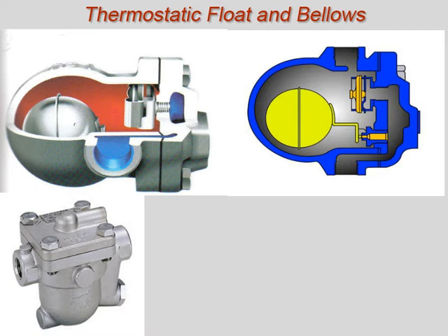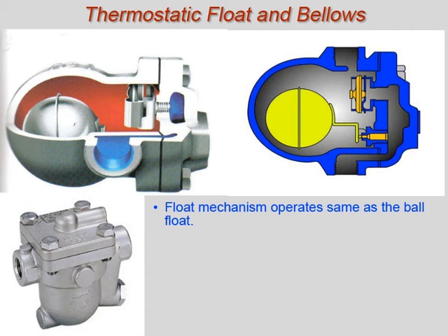The thermostatic float and bellows is a ball and float trap with a bellows vent valve installed. The float portion of the valve operates the same as the ball and float. The vent valve operates by expansion and contraction of the bellows element.